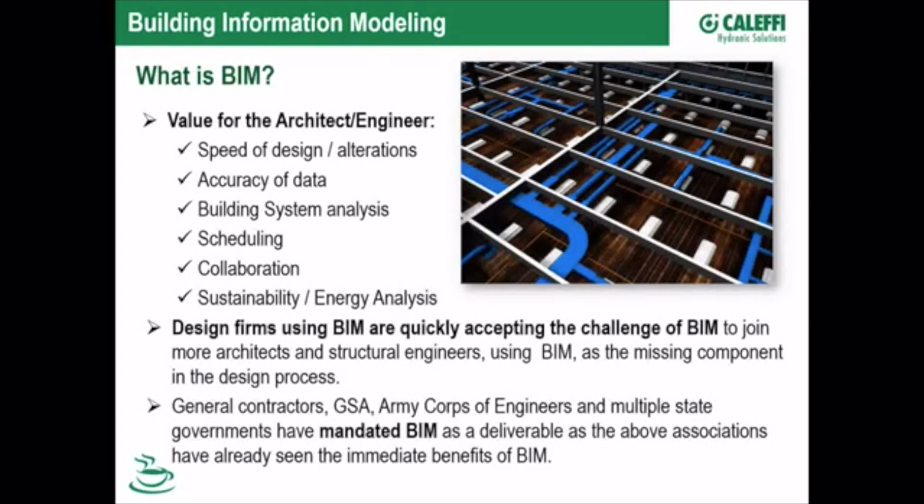Scheduling. Scheduling in Revit is almost automatic, and I say almost because it depends on the quality of content. If certain content is missing shared parameters, it just won't make it into your schedule. Collaboration. Simultaneous participation by the design teams, whether within the discipline or outside of the discipline. The collaboration effort allows multiple users to work on the same project at the same time.